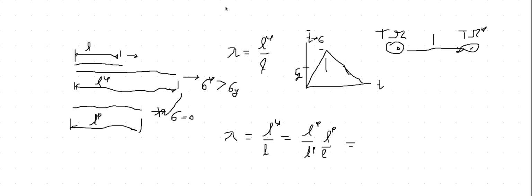And then I introduce some kind of intermediate configuration, where with this intermediate configuration I load, so I have FE FP. And so that precisely becomes that. So going from L phi to 1, this becomes lambda E, because this is precisely how you obtain the difference between L phi and LP by elastic unloading. This is part here. And then what is LP? This is the part which I can never recover. This could be a plastic stretch, which is called lambda P.